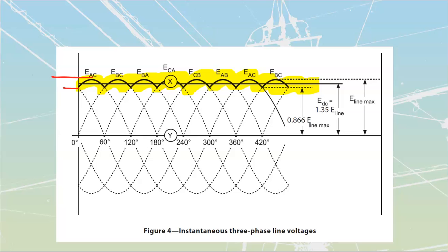You can, in some cases, go and filter that out. If we do try to filter it out for a very large drive where we have to pass a lot of volts and currents through there, it makes for really large components that we would have to utilize, huge inductors and huge capacitors, because those are going to be the two ways that we filter stuff out. You can go back into your second year electronics and we cover filtering, with the different types of filtering, and it would just be applied in the same way into a three-phase circuit.